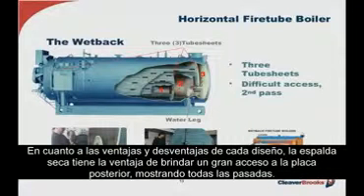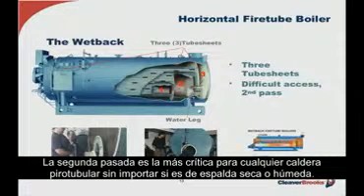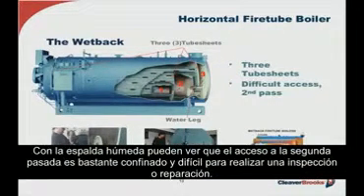Now, as far as advantages and disadvantages for each design, basically, the dryback has the distinct advantage of providing easy accessibility to the rear tube sheet, revealing all the passes, of which the second pass is the most critical in any fire tube boiler, be it a wetback or a dryback. Now, with the wetback, as you can see, access to the second pass is very confined, and the space very difficult to work in when inspecting or repairing.